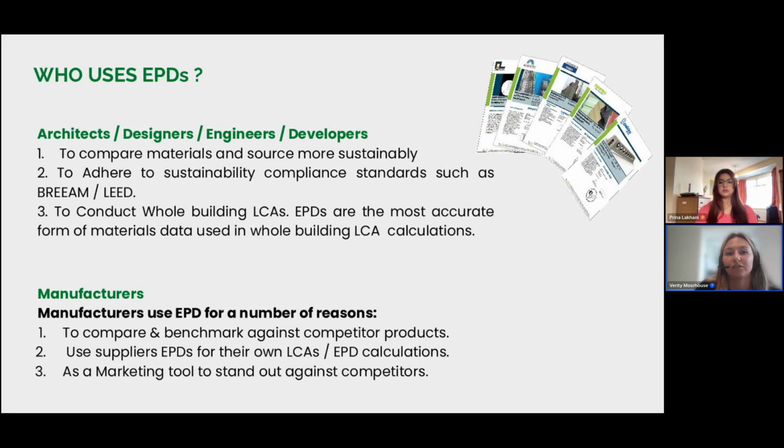They actually get credits for using products that have EPDs, so it can help them to achieve those higher standards. And then, as I mentioned, to actually conduct the whole life building LCA. So again, that could be early stages, or it could be right through to as built and reporting on exactly what the emissions of that total building are.